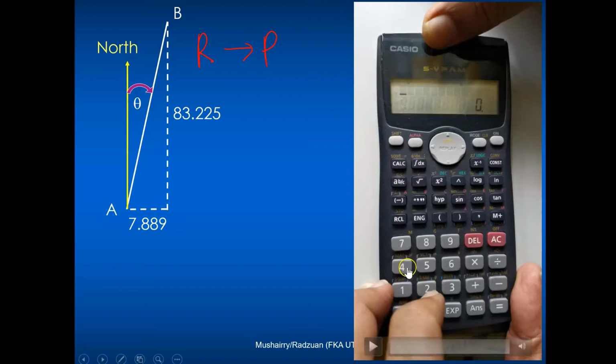If you look at the video now, just bear in mind that number there. There's a difference in northing, and there's a difference in easting. If you look at your calculator, you'll find that the plus and minus buttons have a second function written: REC for the minus and POL for the plus button. REC simply stands for rectangular and POL stands for polar. So what we're going to do now is convert rectangular to polar.